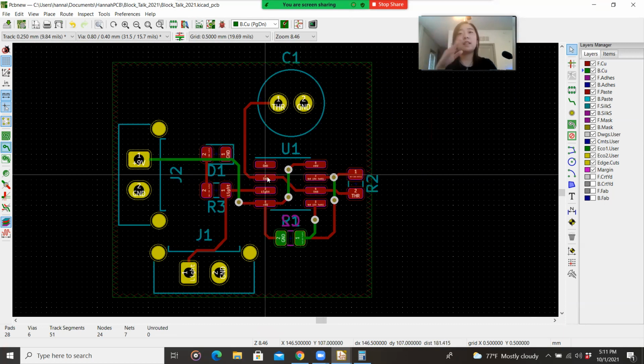Sometimes, a lot of the time actually, that's not going to be the case. Why is that? Sometimes you might create a signal island where there are different traces going this way, this way, this way, so there's essentially a pocket of the PCB that's not directly connected to ground. In that case, you might need to connect it to ground in another way, through certain ground pads. But in this case, it worked out, and we don't have to worry about it.